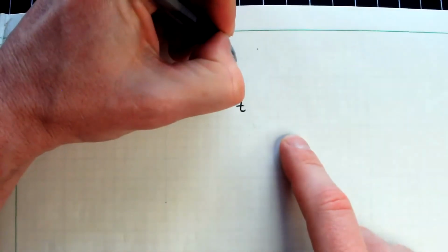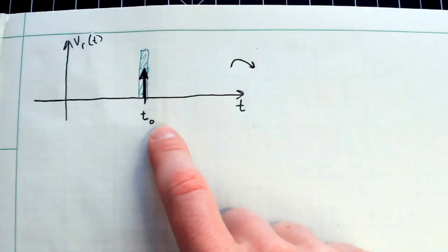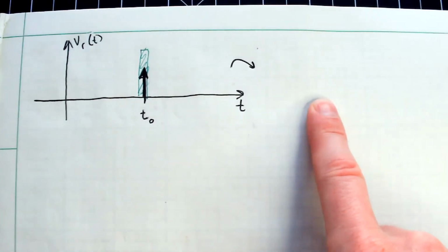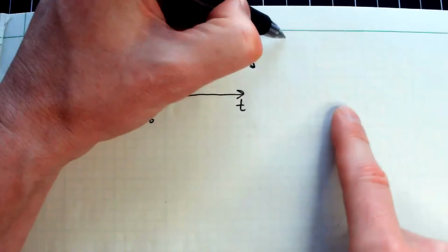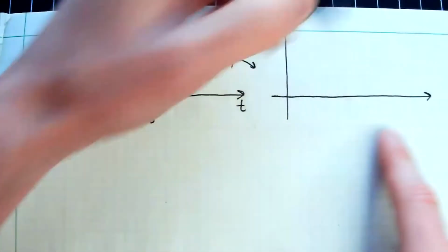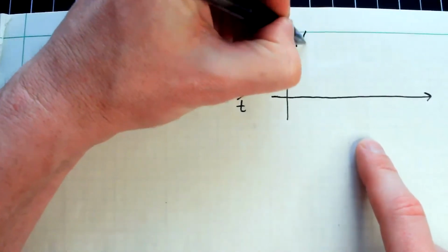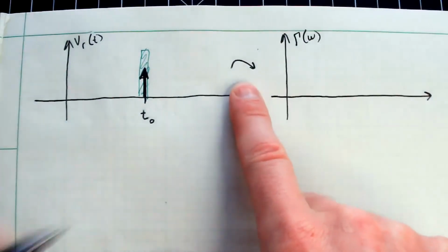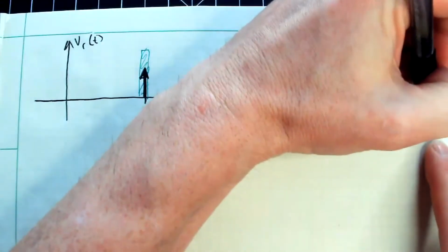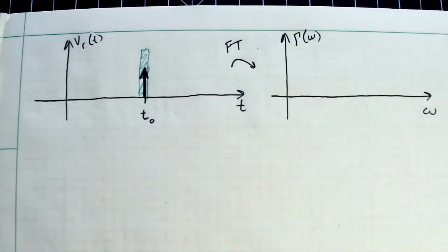So we don't actually measure the impulse response per se. When we do a measurement with the network analyzer, we're actually getting the Fourier transform of this thing, right? So that gamma of omega is actually a Fourier transform, and this is a function of omega here.